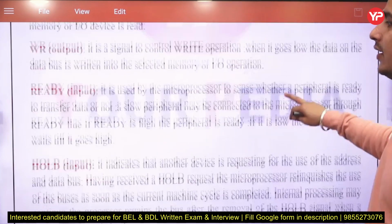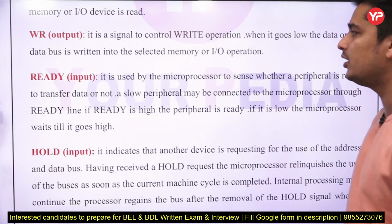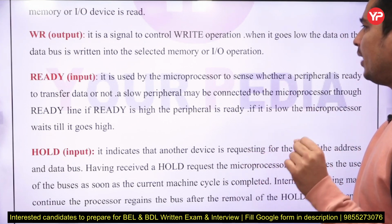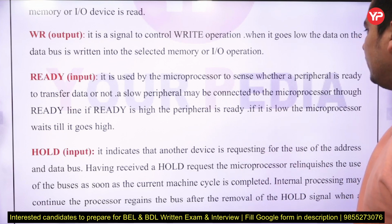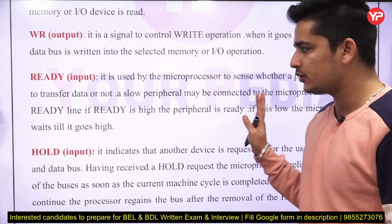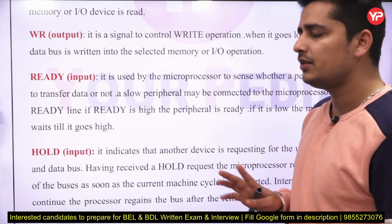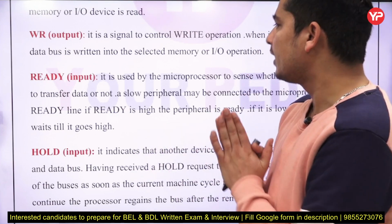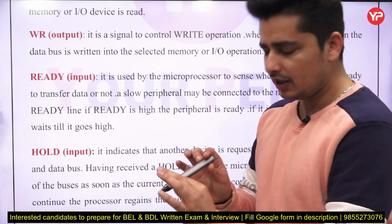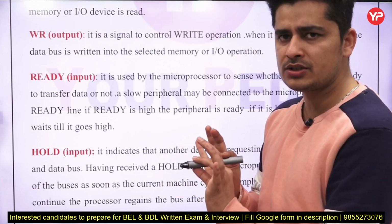Next there is the READY pin. The ready pin is an input pin, where we provide the input. If the ready pin of your microprocessor is low, then the microprocessor will go to the wait state until the ready pin goes up. Whenever you connect an IO device to your microprocessor, the microprocessor doesn't know whether your IO device is ready to perform its operation or not.